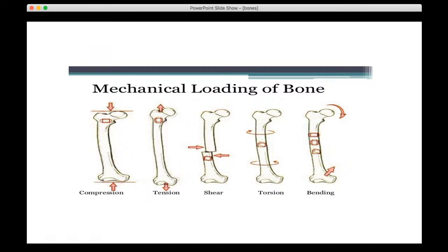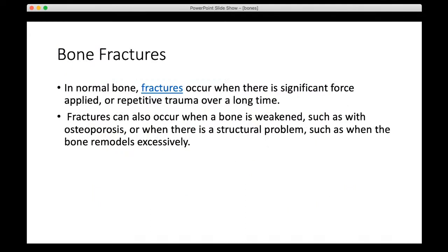These kinds of fractures are common because bones have poor shear strength, and you will hardly see any fracture due to compression. Due to tension there are some to some extent, but you hardly see any case of fracture due to compression. And the most common cases of fractures are due to these three shear stresses: shear, torsion, and bending. So I hope it is clear, the fracture part and strengths. It will become more clear in the later slides when we talk of some curves.